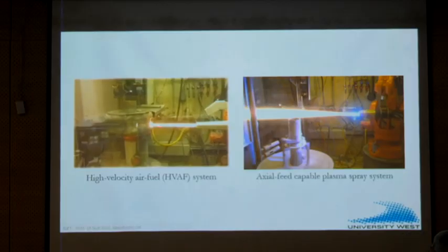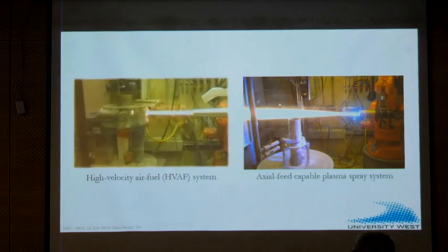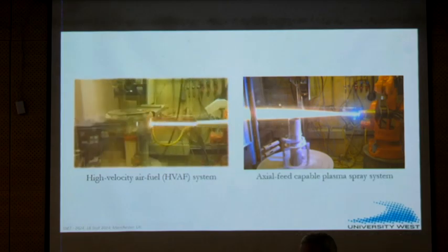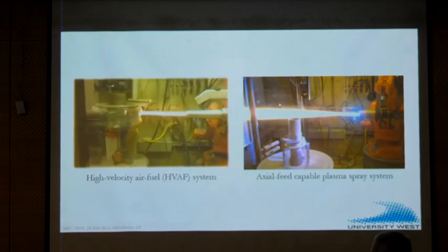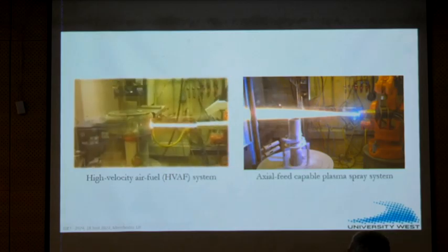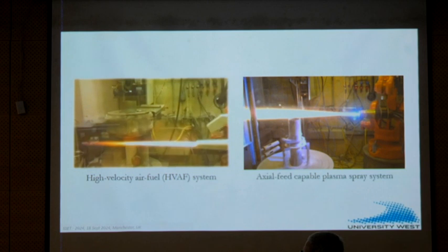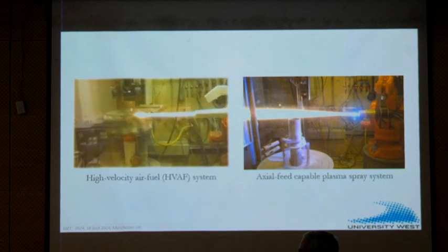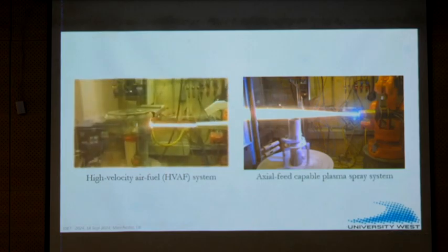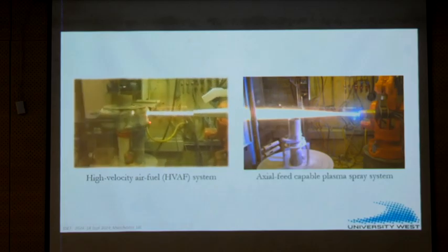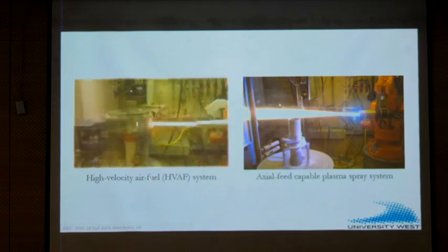For several reasons. One is the inherent deposition efficiency is limited. The coarse particles don't melt, don't plasticize, they bounce off. Then when the gun is on the side, it is still spraying powder, but there is no substrate there. So that is going. Depending upon the size, the powder flow goes like that. The sample is in between, so you may be losing powder above and below it.